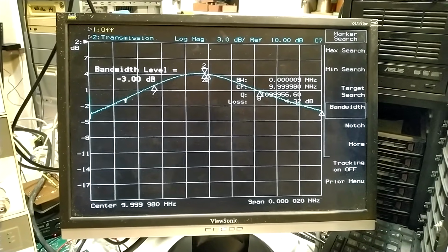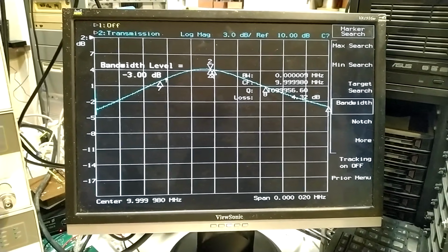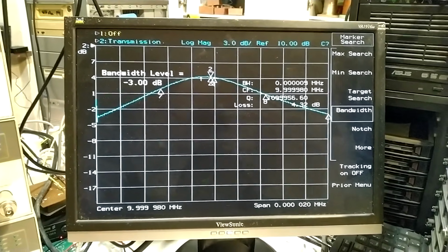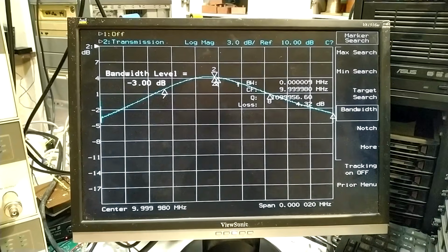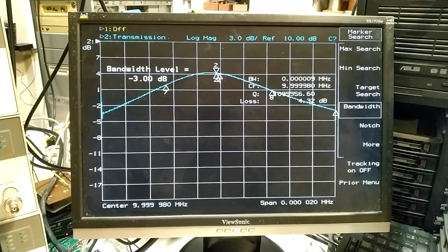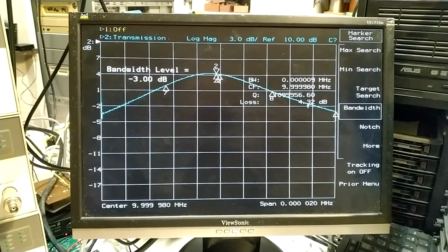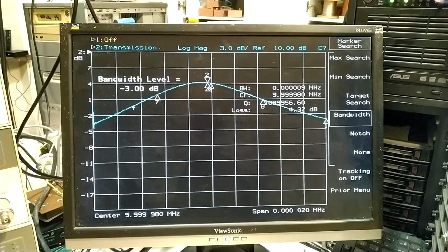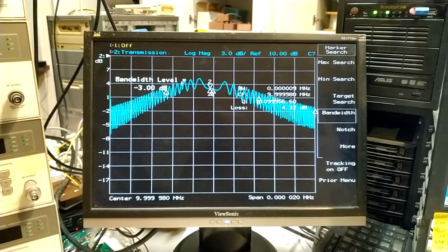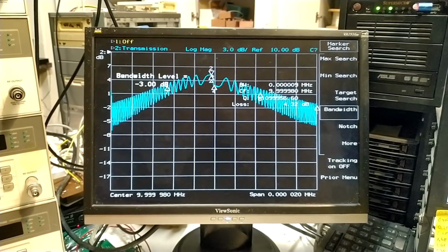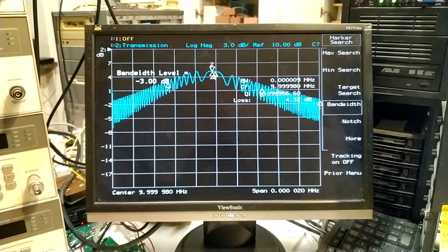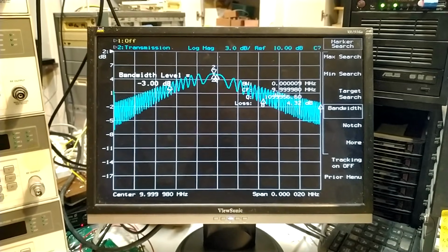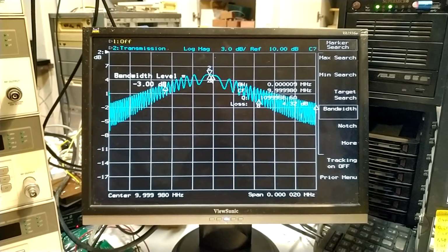The output impedance from the filter is only about 300 ohms, so I have added a transformer transforming the voltage 1 to 3, which gives about 3 kilo ohms into the amplifier. I have verified the frequency by coupling the rubidium oscillator shifted signal very loosely to the input.